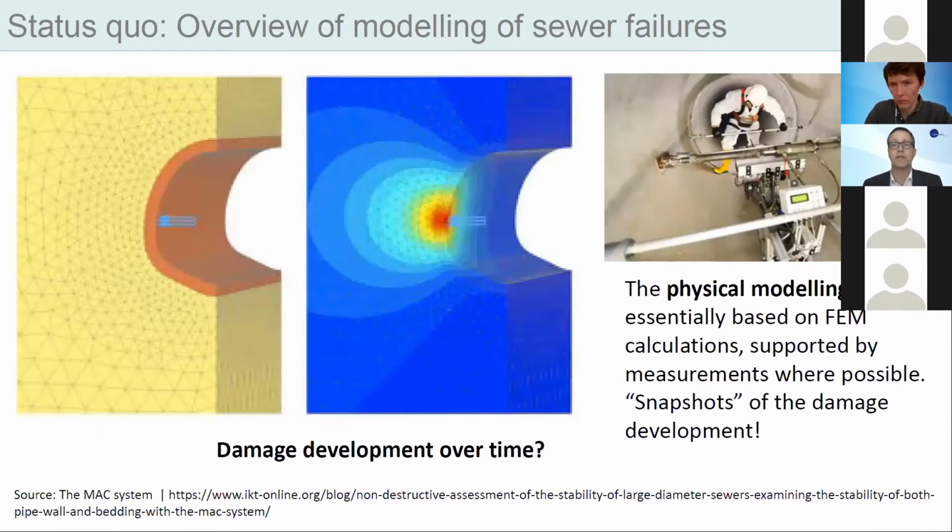So let us now turn to the physical models. And by this, we mean that we describe the system physically and then use this physical model to deterministically describe the individual defined state in its development under load. As a rule, physical models are therefore also very closely linked to numerical models due to the often complex geometries. The most widespread is certainly the finite element method. These models are essentially characterized by 3 components: the geometry, the material properties, and the loading scenarios. In practice, we then try to determine concrete values for these 3 variables. For example, we measure the geometry, we determine the material properties, for example, by testing material samples, and we estimate the loads. The loads can be of a mechanical, chemical, or biological nature. It then depends on the FE, the finite element model, to what extent the effect of these loads on the structure can also be modeled.